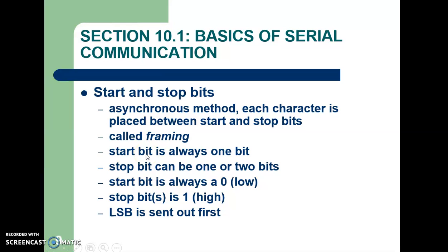So what is a start bit? As we have discussed, there is a fixed set of rules. The start bit is always a single bit. Stop bits can be a single bit or 2 bits; 2 stop bits can be there or 1 stop bit can be there. The start bit is always a 0, low. The stop bit is 1, high. The LSB is always sent first.